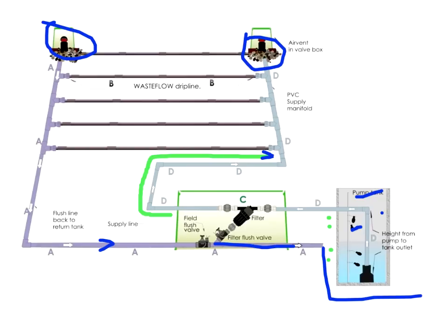The second thing, if the pipe's full and you've got bacteria in the pipe, we know that in the secondary treated effluent, there's a fair amount of anaerobic bacteria. When you switch the system off, they've got a lovely, happy breeding ground, and you're going to breed bacteria at a tremendously high speed. And of course, if anybody goes on vacation for a week or 2, they're going to come back and their drip line is going to be filled with bacteria.